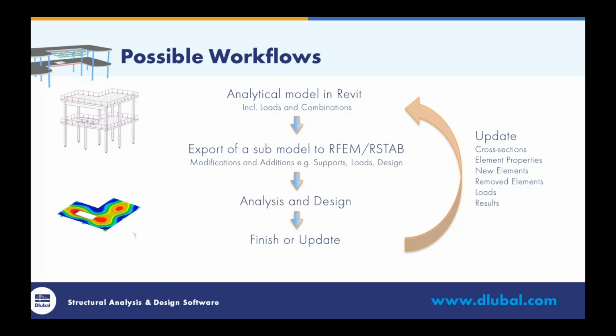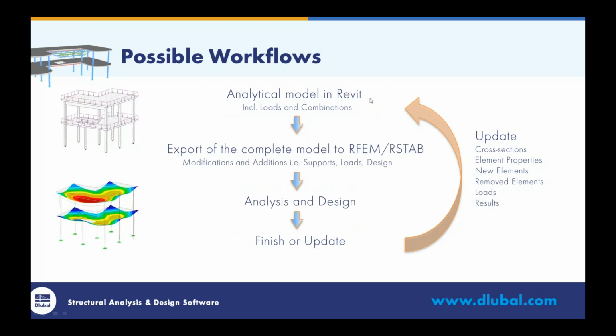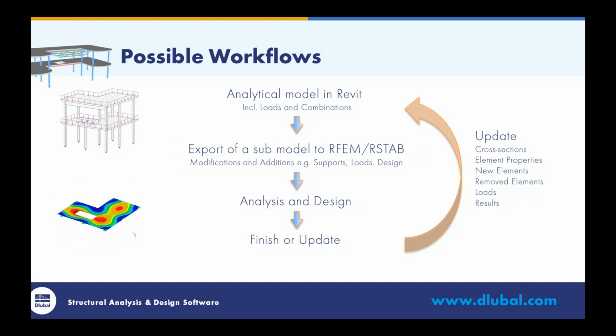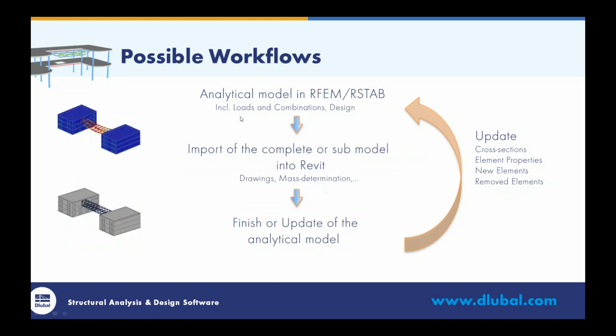These workflows, I mention here usually Revit in this document, in the PowerPoint. They are, however, applicable to Tekla as well. So the first and the second workflow are more or less identical with Tekla. Only the third workflow, where we start in RFEM and export to Revit, we do not have that option to update the RFEM model in Tekla. So whenever I export from Tekla to RFEM, I will create a new file. Only Revit offers me the option to update my RFEM file.